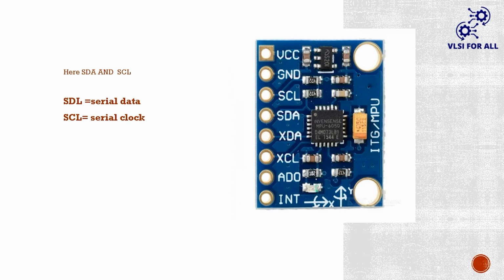You might have seen some sensors which have SCL and SDA pins. These SCL and SDA pins are used in the I2C communication method to communicate with the microcontroller. Before going to I2C, we will consider an example.